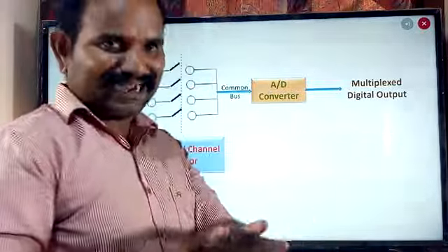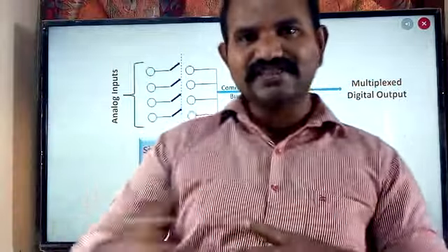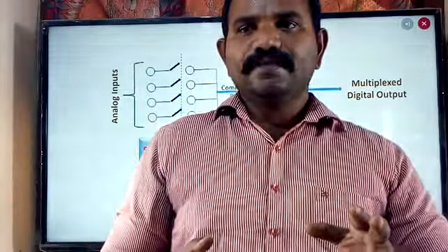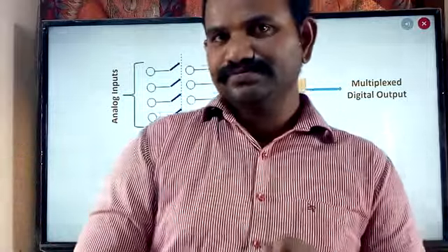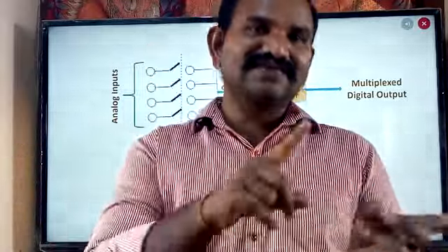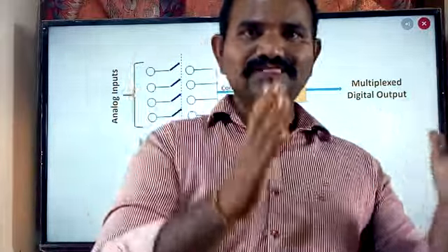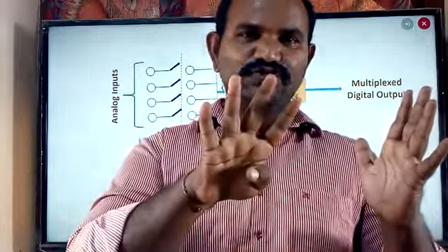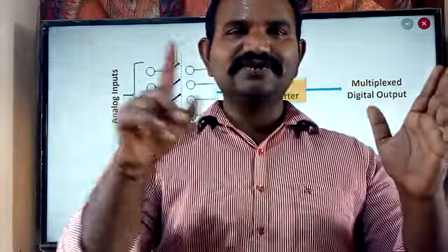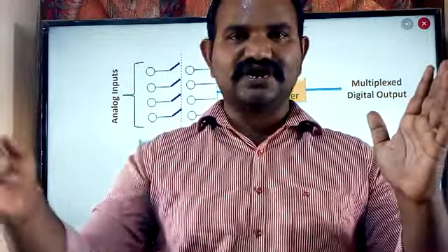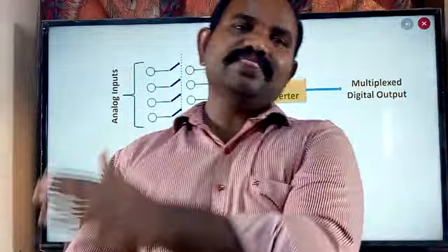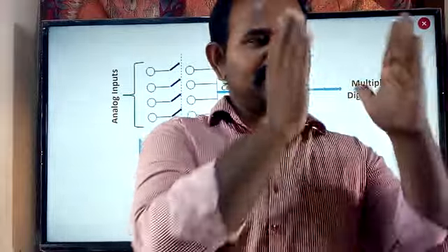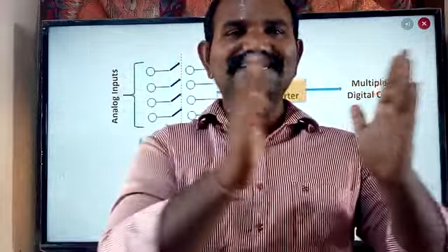Okay, so just like that. Here also, when the multiple signals would like to send the information, don't think that multiple signals are sending the information at a time. Even though they are trying to send the information at a time, there is a time slot. What I mean to say is that if we are having 1 minute of time period allocated for all the channels, then that time period is equally divided among the number of channels. So let us suppose I am having 4 channels, then the 1 minute duration is divided into equal parts. 1 minute is 60 seconds, then 15 seconds for each and every channel. So after that completion, the first channel is going to get its turn in the next 15 seconds, means 15 seconds for each and every channel. It is called time slicing.